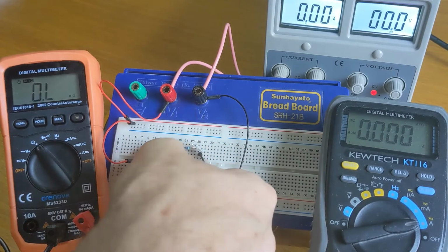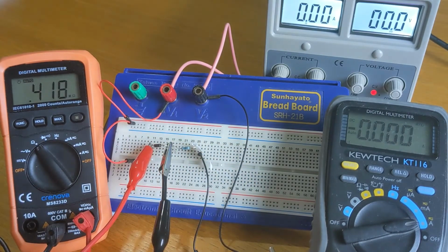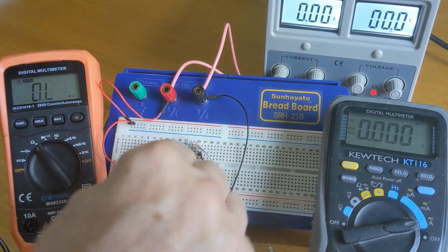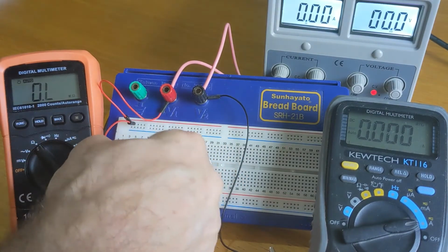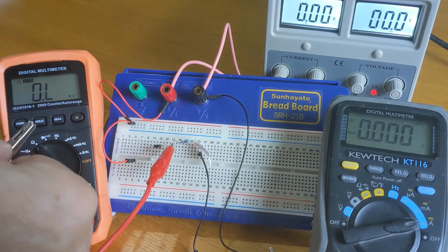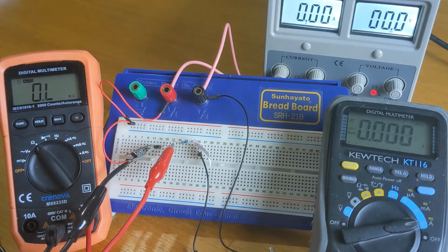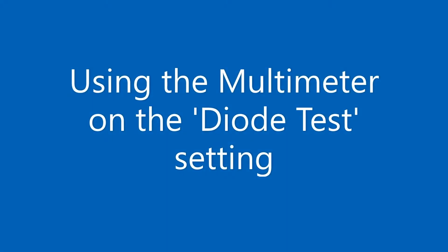Let's have a look at the resistance of the diode itself. In forward bias, it has a small resistance at the small current that's going through it from the multimeter, but it will conduct current in that direction. If we put it in reverse bias, then the small current coming from the digital multimeter cannot go through. It says OL for open loop, effectively a very large resistance.